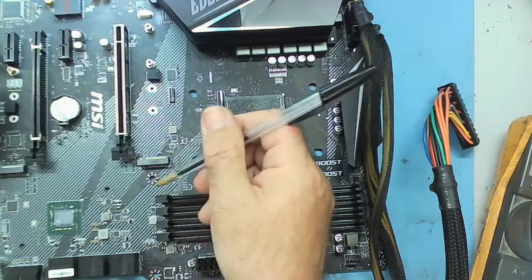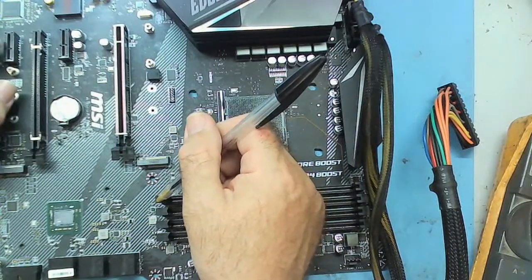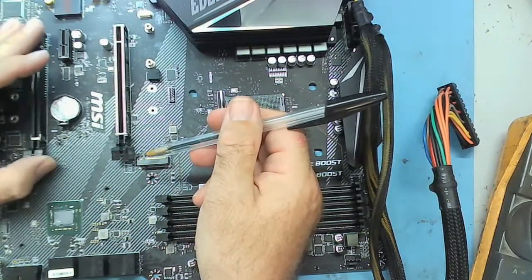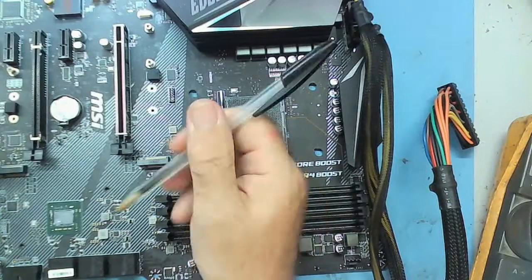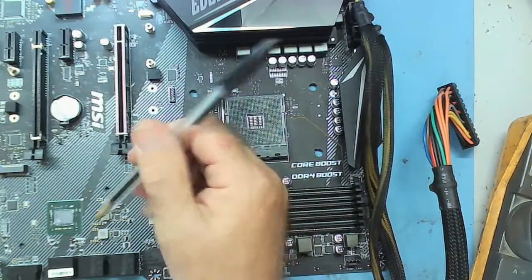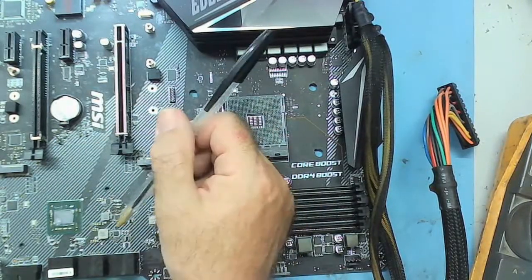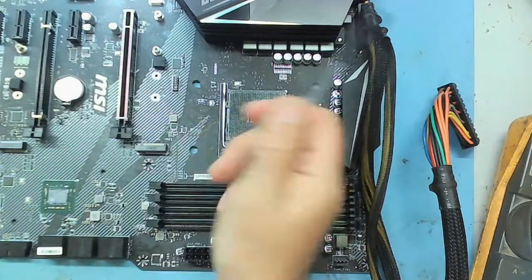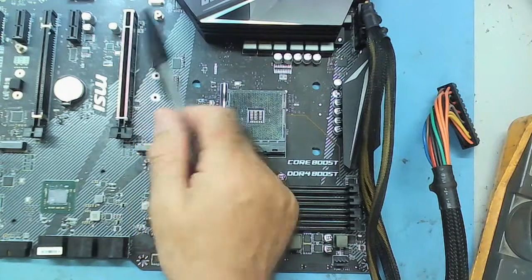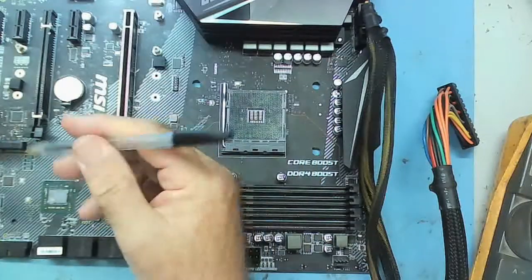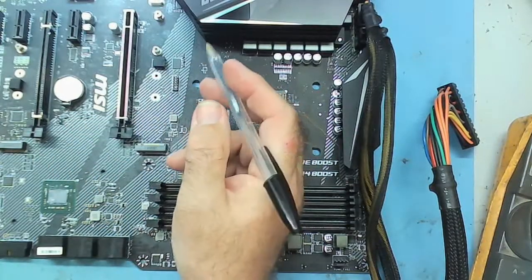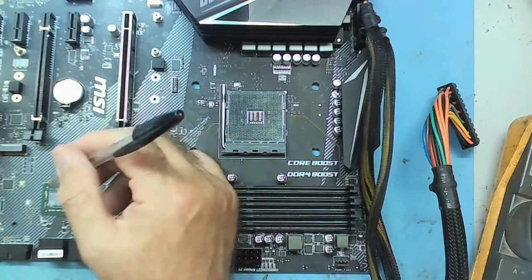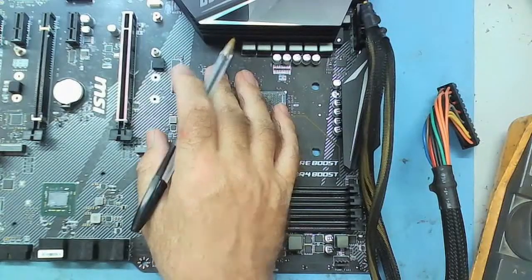That's method 2. Yeah? Method 3, go on the internet forums, bad apps, EveBlog, and ask, anybody see one of these, could you tell me what these voltages should be? So that's 3 ways you can find out. Are they right or are they wrong? Fourth way, if you're really stuck, you'd have to stick this on one side till you come across another board with the same chipset and then compare the voltages, which is what I just did. Buy another board, another 40, and hope it's not the same problem. However, you may have to stick it on one side. So that's how.